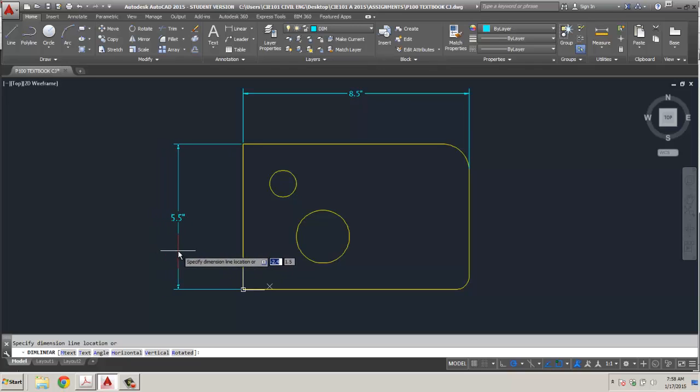You can specify, but really it's more about just trying to make them look as close as possible. We have a dimension from, if you hit enter, you can just repeat your last command. Another cute little tool. See how it finds that center point? We can pull this out now a little closer, and we're going to do this, hit enter, repeats that dimension again, go to that center point. We're going to pull this one up a little closer to that overall line. We're going to do the same thing now.